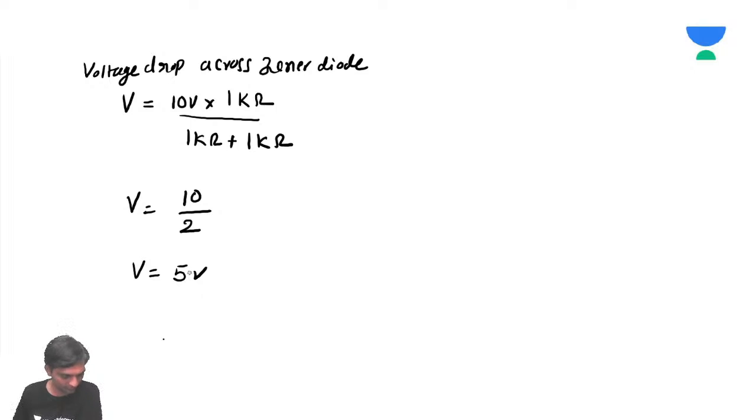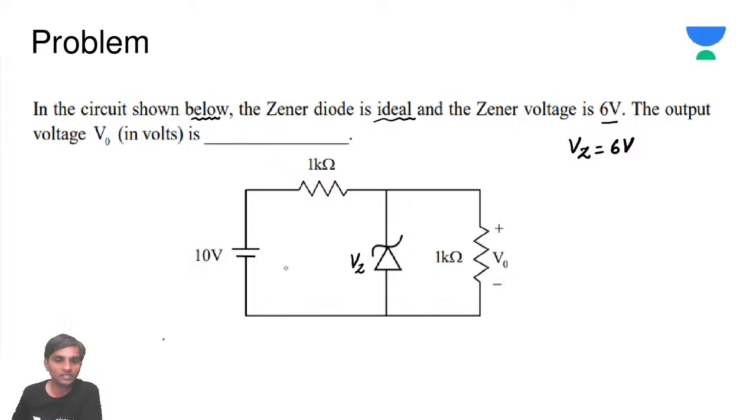5 volts. Balaji, good. Sir, what is the Zener voltage? Vz. The voltage you are applying here, Krishnavedi, what you might have thought is that this 10 volts is across the Zener diode. This is what you thought, right? But you should consider the voltage across the Zener by considering the voltage drop across this 1 kilo ohm also.